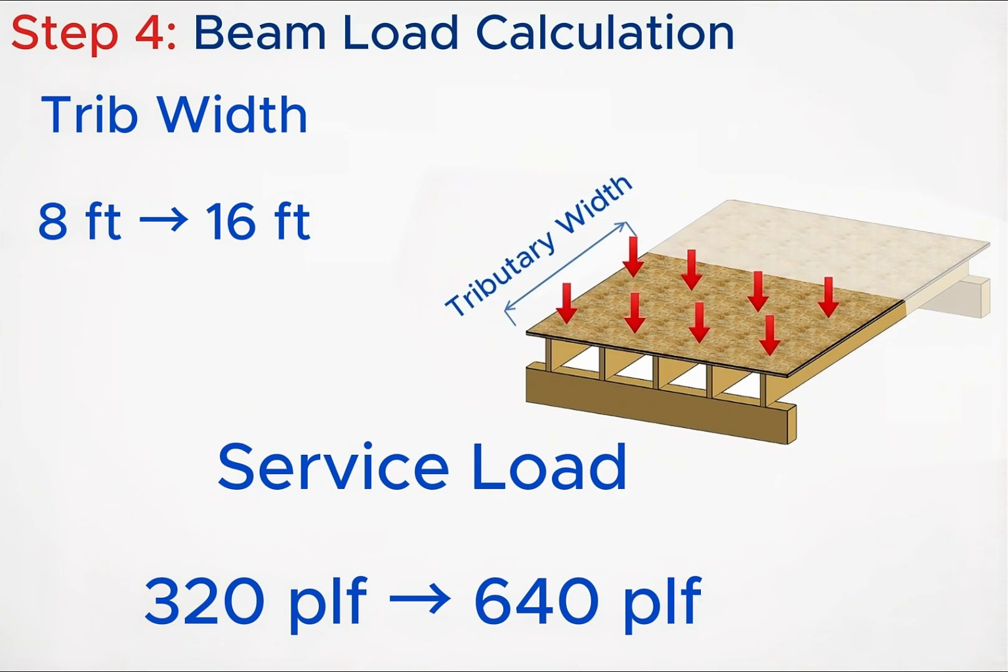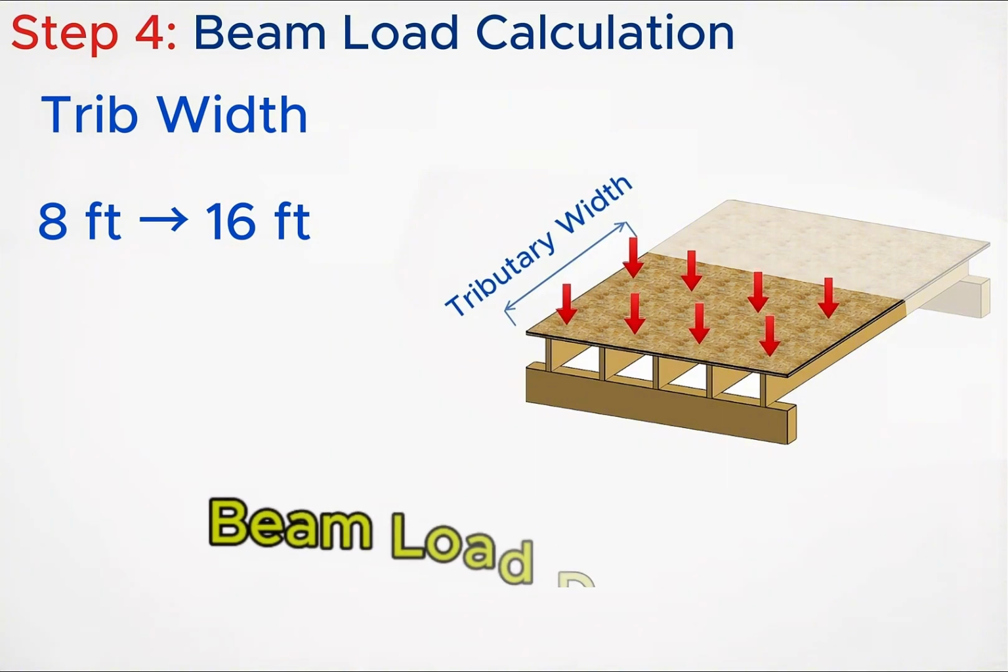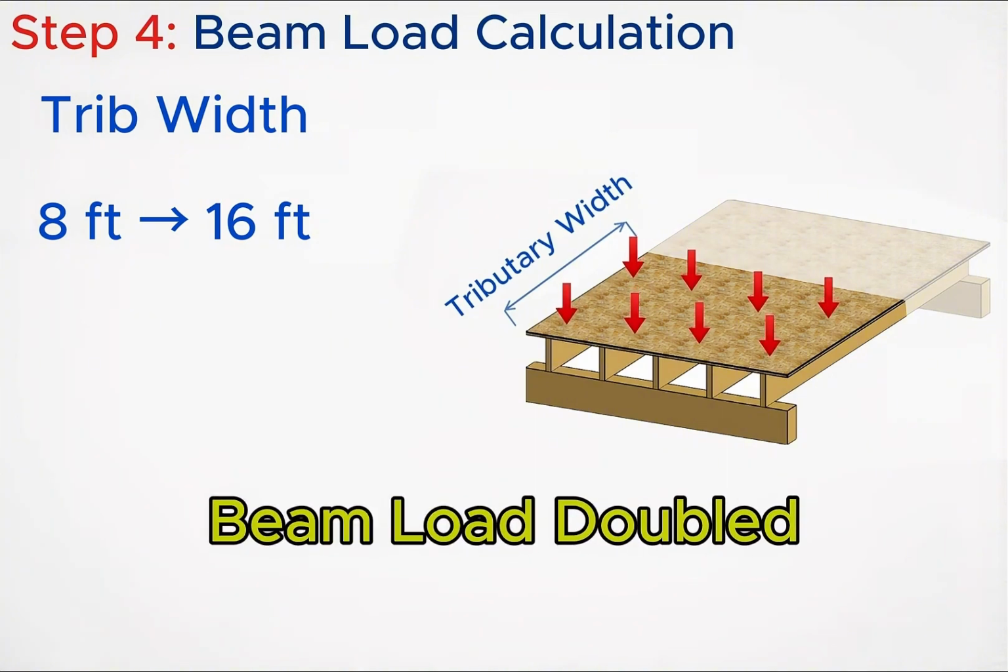Notice what happened. The load values didn't change. The material didn't change. The code didn't change. The only thing that changed was the tributary width. And suddenly, the beam load doubled. That's why tributary width is one of the most important concepts in structural design.